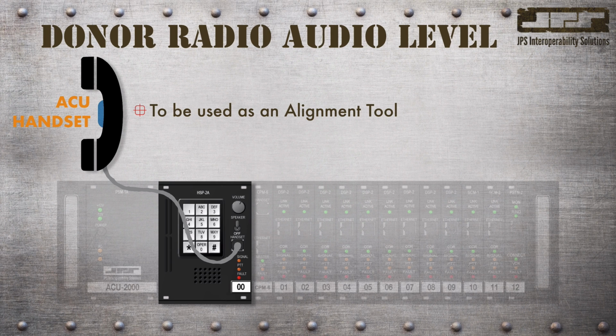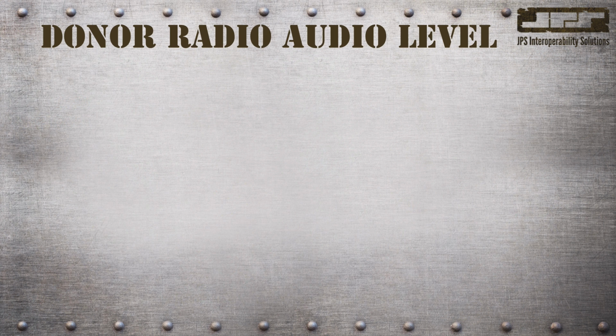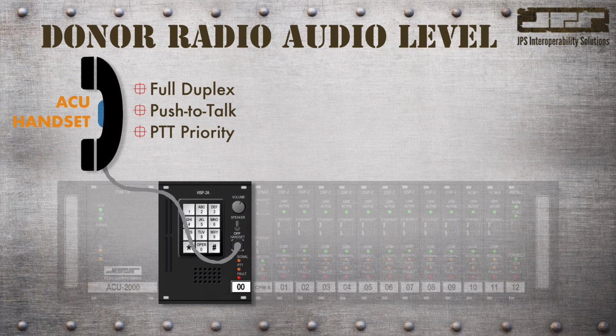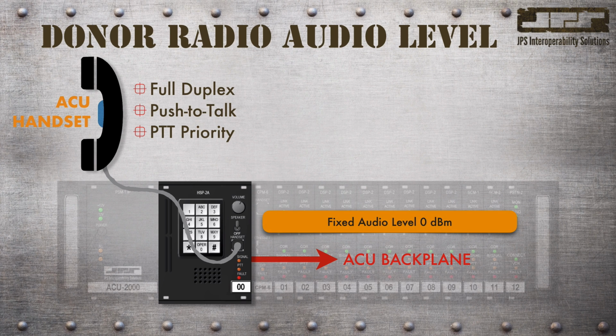An important tool that we'll be using during setup and troubleshooting activities is the ACU handset and the backplane. All ACU gateways are equipped with a push-to-talk handset that allows the operator to listen and converse with any of the radio and telephony systems associated with the ACU gateway. The handset has full duplex PTT priority, which gives an operator the ability to break into any conversation at any time.